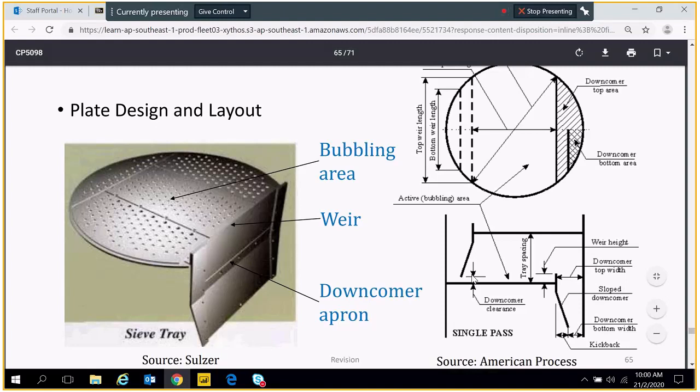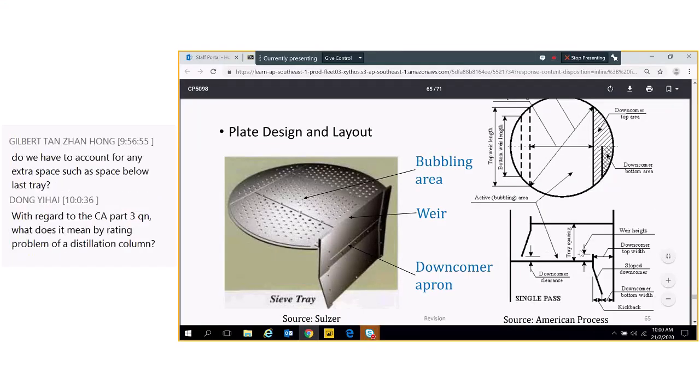That is liquid flooding. How can you have liquid flooding? You have liquid flooding when vapor velocity is very high. A lot of vapor rushing in pushes the liquid level up. A lot of gas bubbles inside push up the liquid level until the liquid touches this tray. That is called flooding.